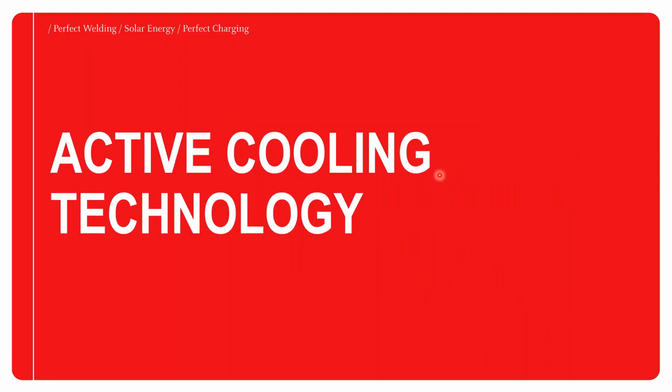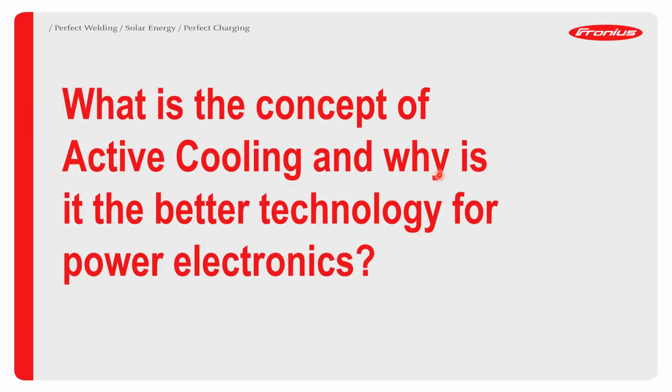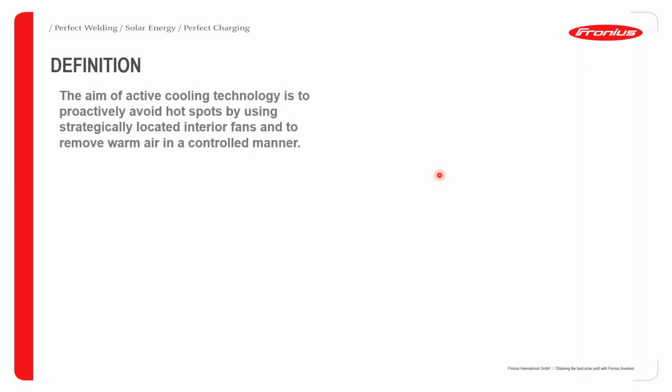All right, so let's now look at something else that is also very, very helpful in Fronius inverters that guarantees you maximum yield, and this is the active cooling technology. So what is the concept of the active cooling technology, and why is it better technology for power electronics? By definition, the aim of the active cooling technology is to proactively prevent the creation of hotspots, and this is done by strategically positioning interior fans to remove warm air in a controlled manner.